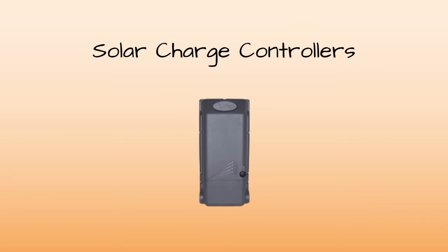Here's an example of a high power solar charge controller from Outback Power. This type of unit can be used in a system to power homes in an off-grid environment. The voltage input from a much larger solar panel array than the previous examples can range from 230 to 290 volts DC. This unit can operate with either 24, 36, or 48 volt battery banks. This one provides a continuous output current of 100 amps for 5 kilowatt battery charging and is equipped for operating in large systems.